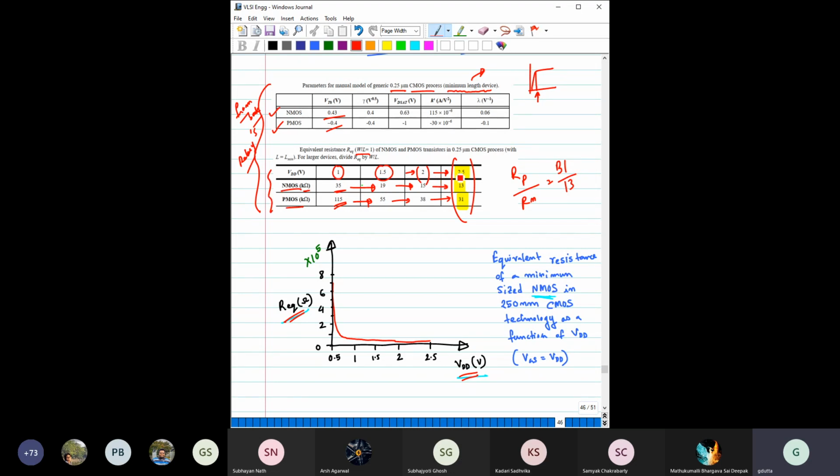So when you are plotting, suppose we are considering VDD equal to say 1.5, then at that time for this case we will be taking ID and VDS. This VDS is VDD, 1.5 volt, and here VGS would also be equal to 1.5 volt, right? Because if this VDD supply voltage itself is 1.5, then VGS also has to be equal to 1.5 only, right? So please do remember that if it is 2, then you have changed it to 2 volts.